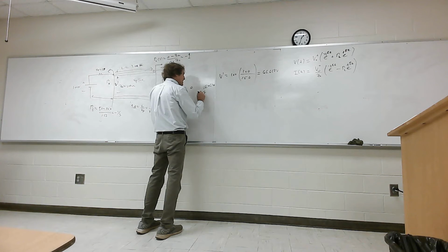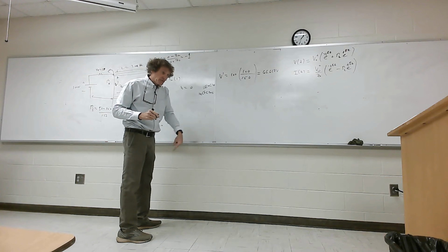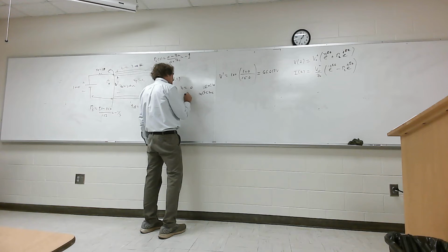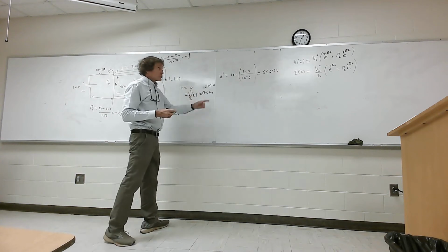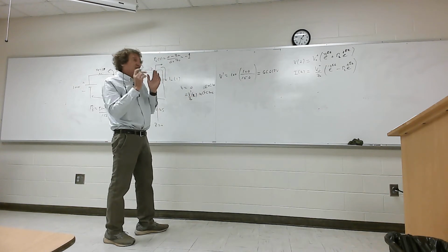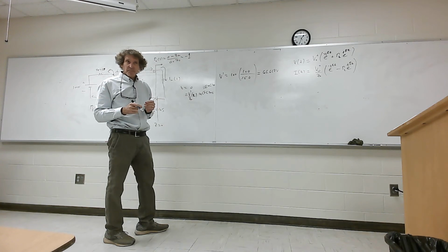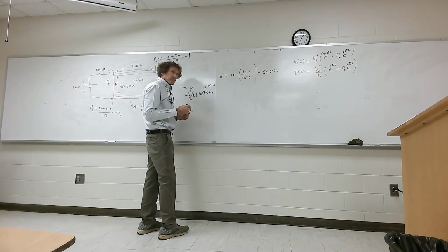Then for t greater than 1 microsecond and less than 3 microseconds, because it's 1 microsecond down, then bang, 2 microseconds back, 3 microseconds, it's going to be a value of V prime over Z naught times 2 right here. That's because 1 minus the reflection coefficient gives me this value. Do you all follow me on that, class? That's going to be true for 1 to 3 microseconds.